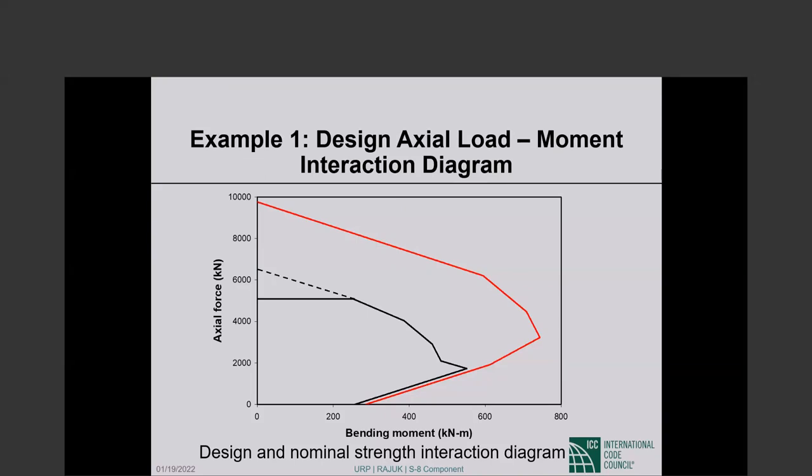Like if there is a steel shape in a column, as I mentioned earlier, there will be redistribution of forces between the concrete and the steel. Basically what I'm trying to say is that the shortening of this composite column may be different from the shortening of the other columns, particularly after a number of years. The time dependent part will be different, and that may cause problems.